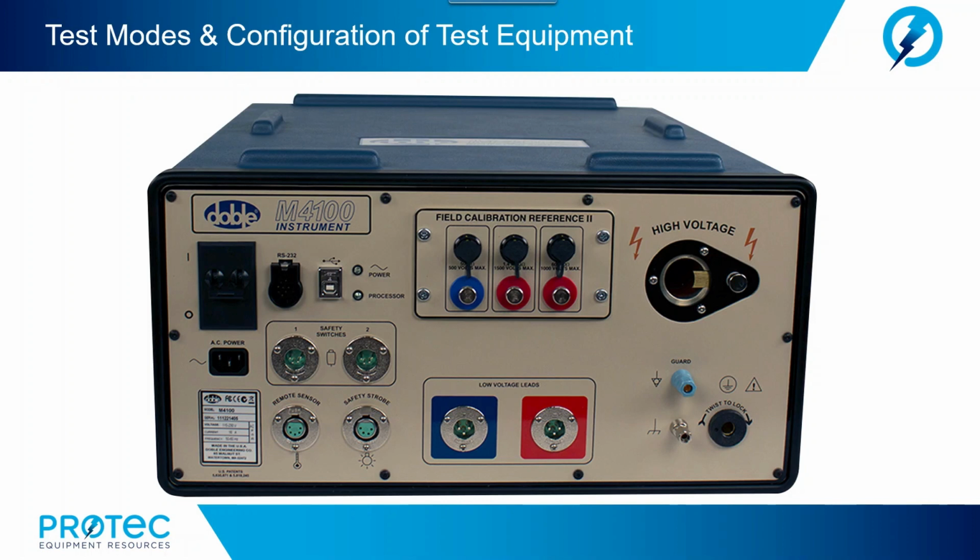Power factor tests can utilize two low voltage leads and a ground lead simultaneously. We're going to use the Doble M4100 as our base model, but keep in mind, most power factor test sets or dissipation factor test sets will operate in this same manner.